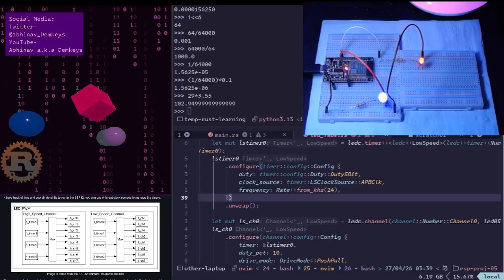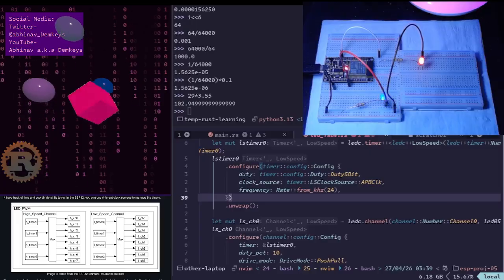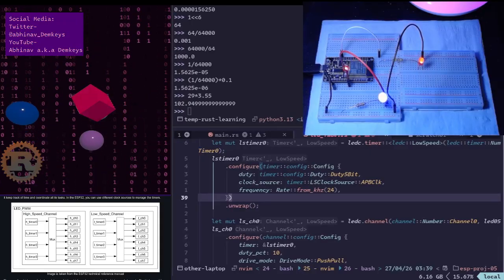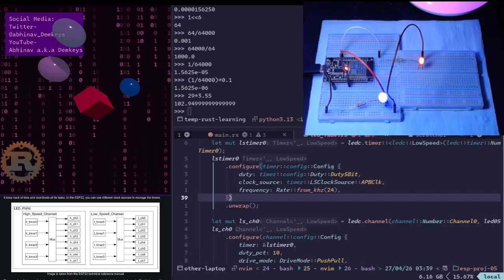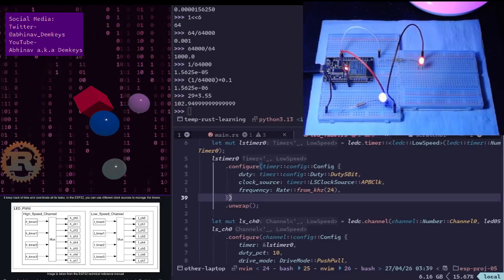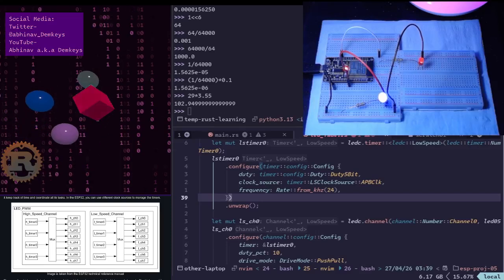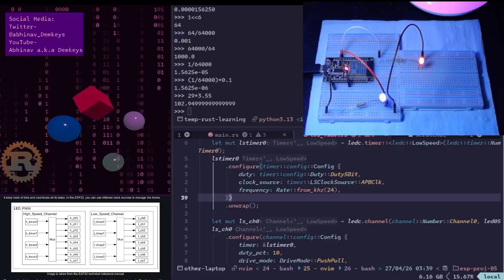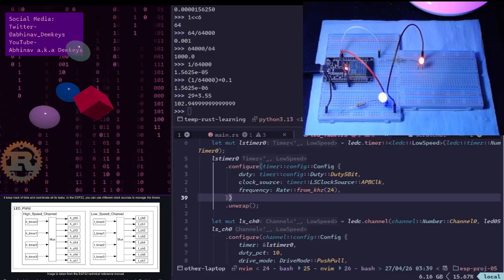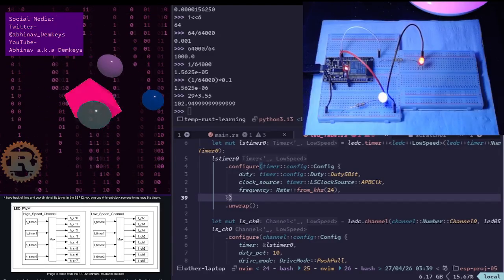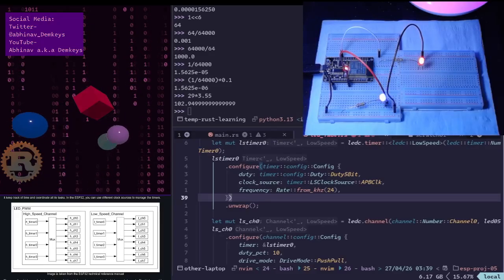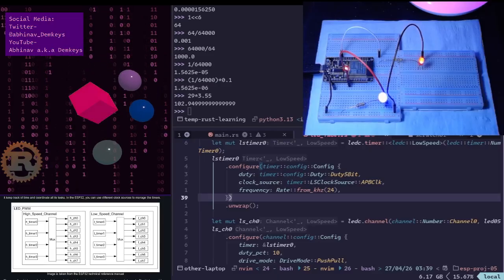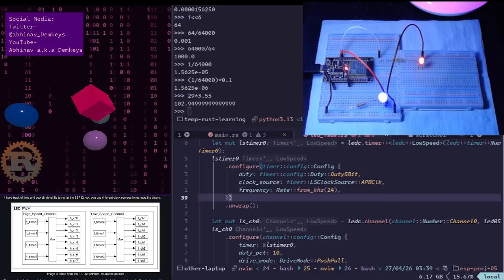Other hardware that works while the CPU naps. Beyond PWM, several other modules can operate with varying levels of independence. Hardware timers, these are dedicated counters. You can set a timer to count down from 10 seconds. The CPU can go do other things or sleep, and the hardware timer will fire an interrupt, an electronic alarm, to wake the CPU up only when the time is actually up.